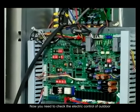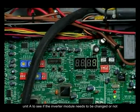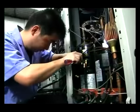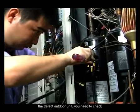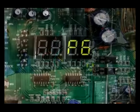Now, you need to check the electronic control of outdoor Unit A to see if the inverter module needs to be changed or not. If outdoor Unit A cannot start normally, that means the compressor has a malfunction and needs to be changed. If there is no other outdoor unit of the same series near the defective outdoor unit, you need to check and repair as follows before changing the compressor.